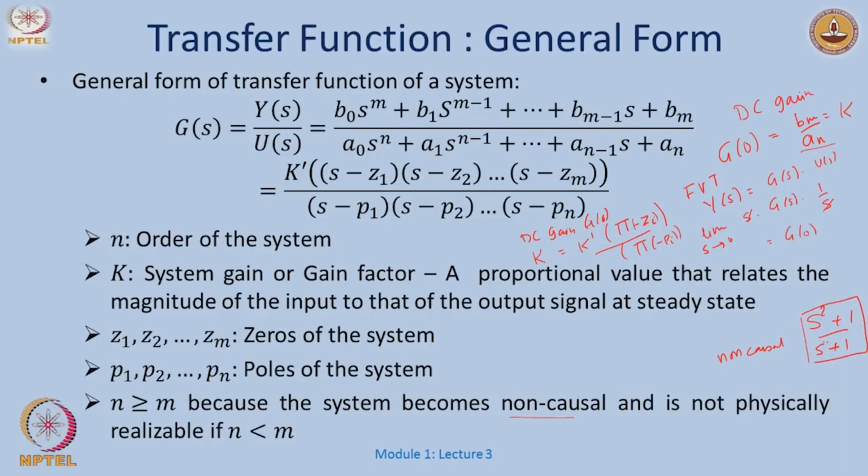You could also look at it this way: if I try to compute the inverse Laplace transform of this, (s squared plus 1) over (s plus 1), it will not exist. Similarly, if I take even a simpler one, s. And therefore, in future classes when we are designing a controller, if you analytically say, well, I got a beautiful controller which has a structure like this, well, this is incorrect. This will never be physically realizable.